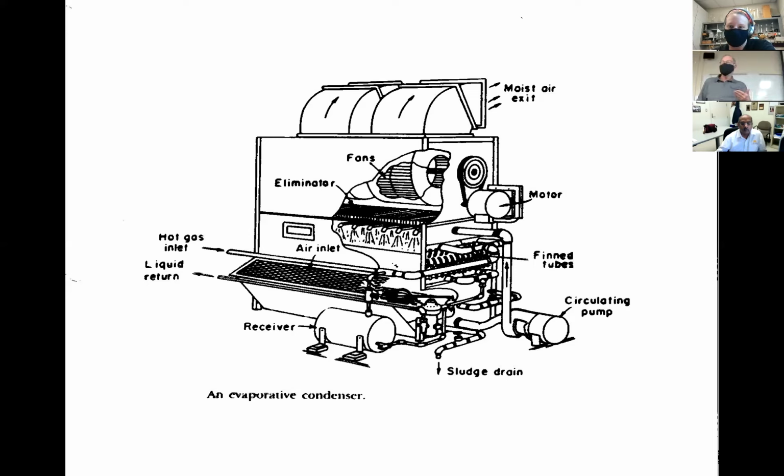They had water puddling there from this moist, hot air coming out. The bacteria were growing away. And then the air inlet into the hotel was in a strategically bad place. So they started sucking that air right back in.